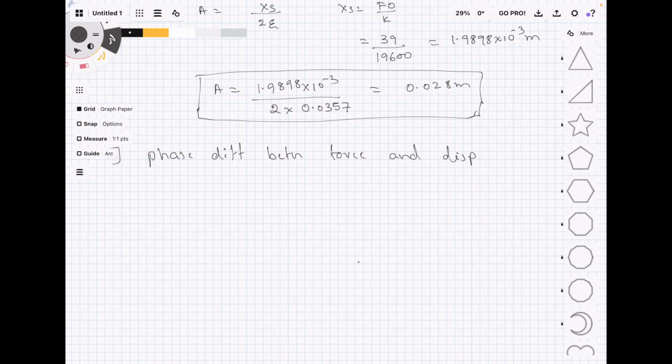In that we had plotted a vector diagram: the k vector, that is ka, the velocity vector, that is ca omega, and the acceleration vector, that is ma omega square. This was the forcing function.